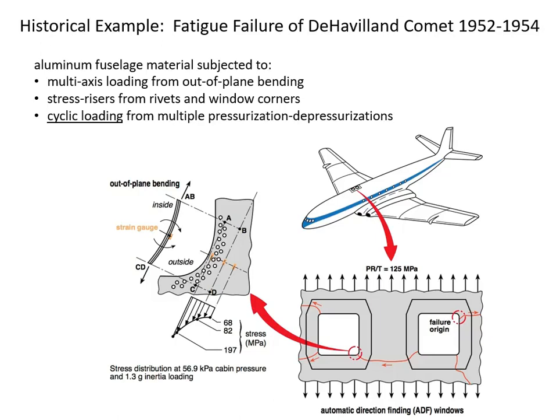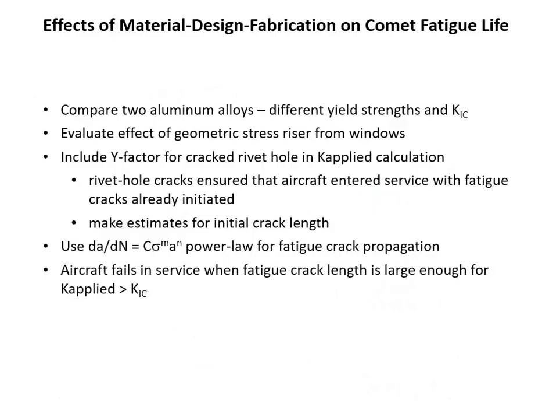And it turned out retrospective analysis showed that when the plane first went into service, after the first few takeoffs and landings, it was already well into the propagation stage of fatigue crack growth. So unfortunately, very few of these ever attained anywhere close to their design life. On the good side, it led to quite a significant redesign in aircraft windows, which has kept us all safer.